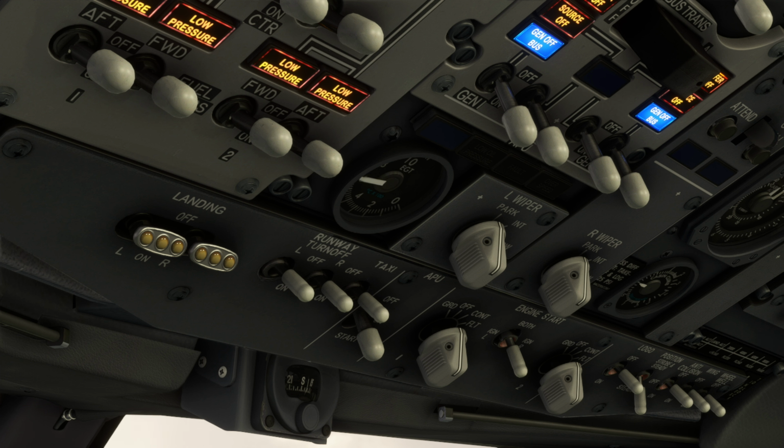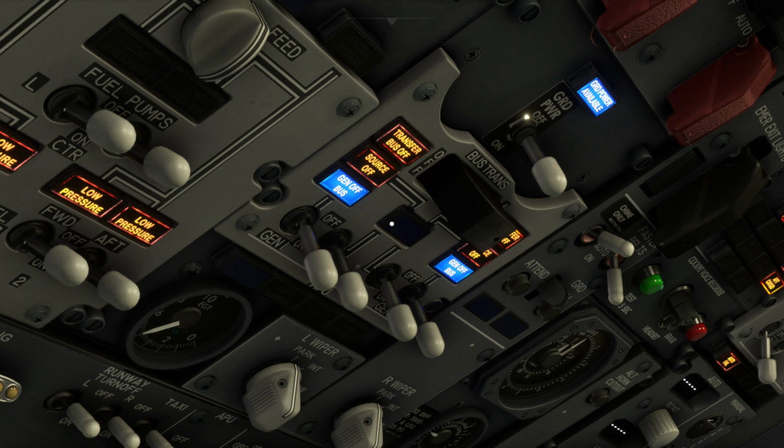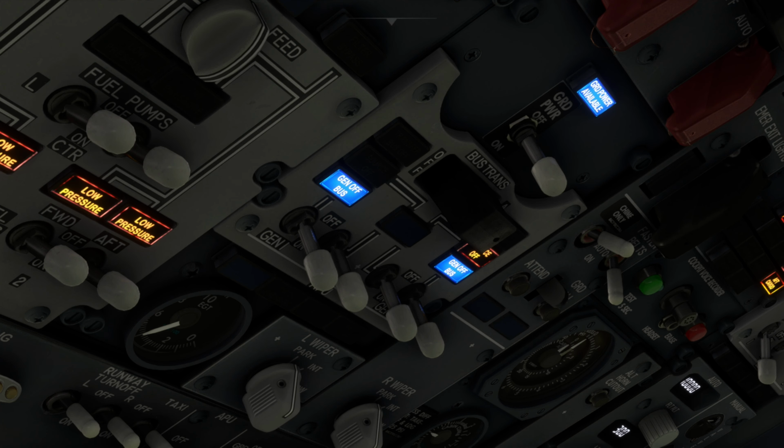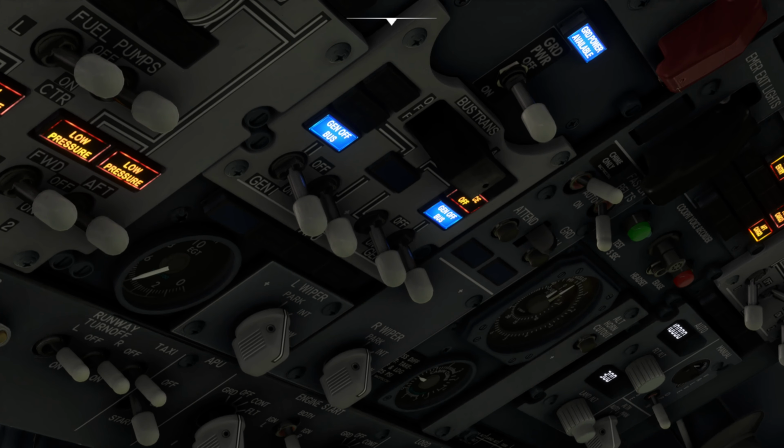We'll expect things to stabilize at around 400 degrees C on the EGT. We'll also expect to see, in the center of this bus transfer panel, APU gen off bus, and there it is. We can bring the APU gen online. And now the airplane's electrical system is running off of the auxiliary power unit, which is really good.